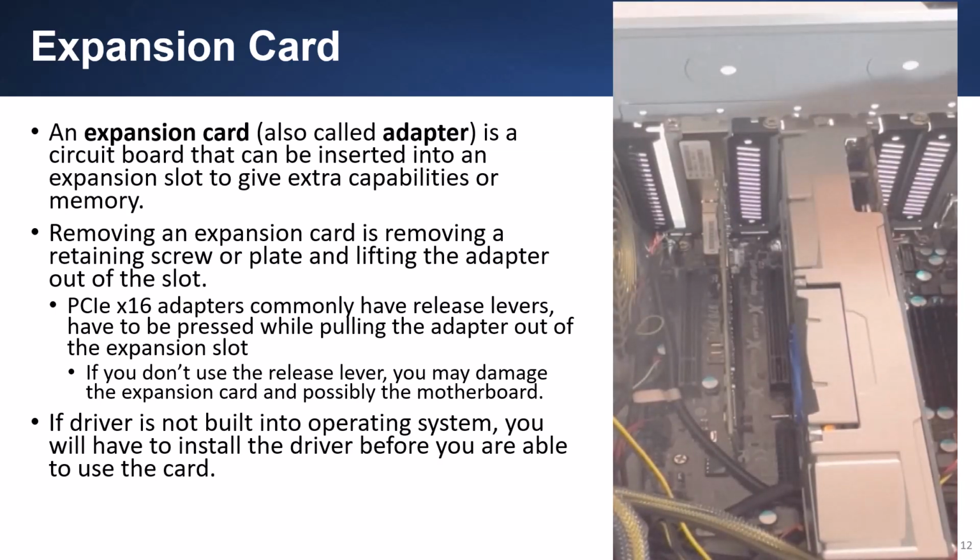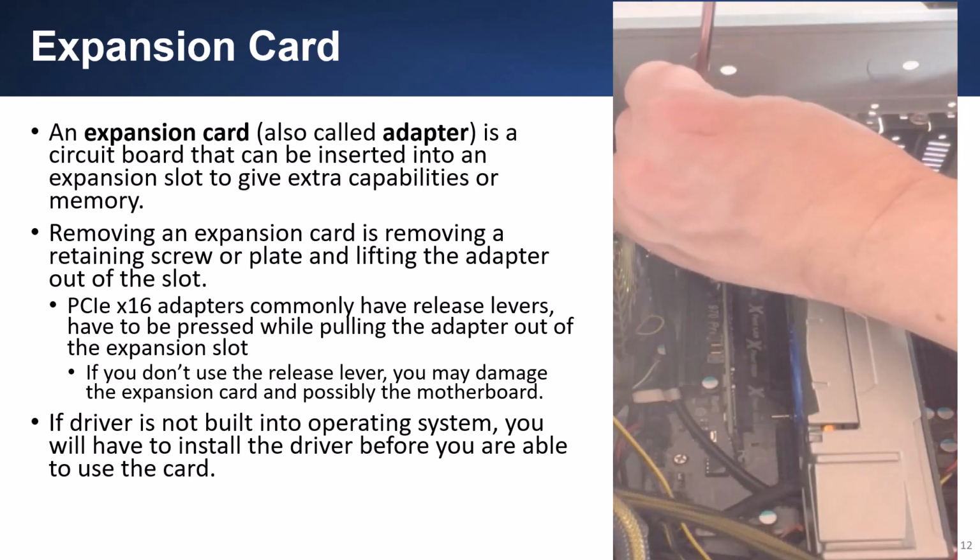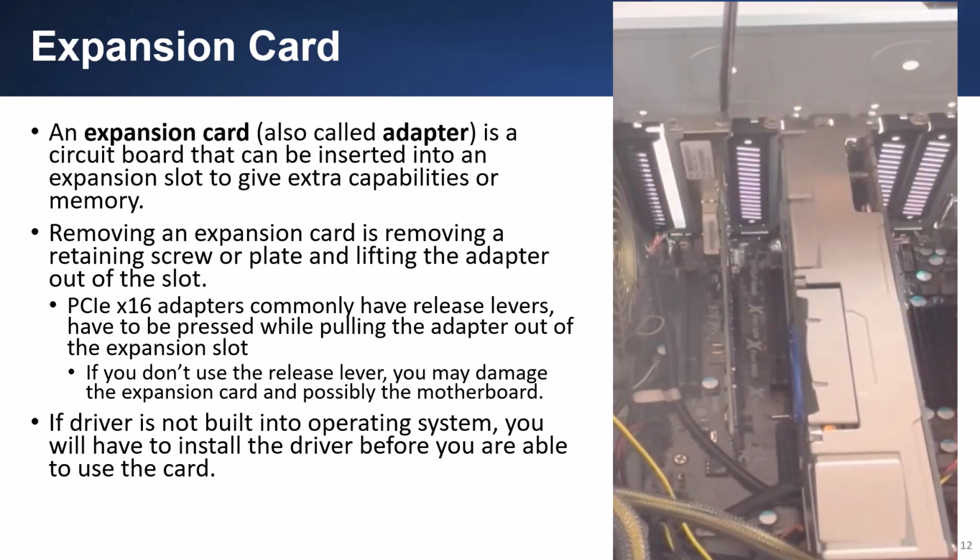Then screw the retaining screw, which will hold the expansion card into place. PCI Express x16 adapters often have a release lever that you must press to release the card. If you don't use the release lever, you may damage the expansion card and/or the motherboard.